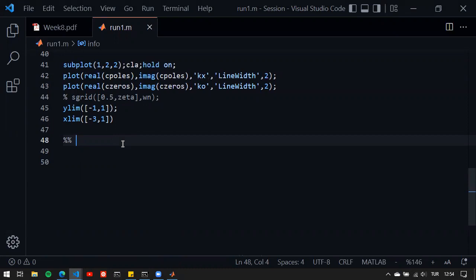Now what we can do is we can do the following. We have a PID controller, but what if we use a PI-PD controller, or if we update our PID controller a little bit? Because we will again have the proportional part, integral part, and derivative part, but the aim here is to get rid of the zeros effects. So how can we do that?